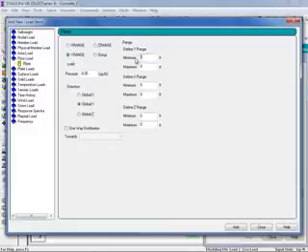So I'm going to enter my minimum and maximum values at 14 feet for my global Y direction, and then the last thing I need to do is select a distribution. Now by default it's going to be a two-way distribution, so it's going to apply the load in two ways to the surrounding beams, or I can select a one-way distribution if that's more applicable to how I would expect the loads to be distributed in my particular model.